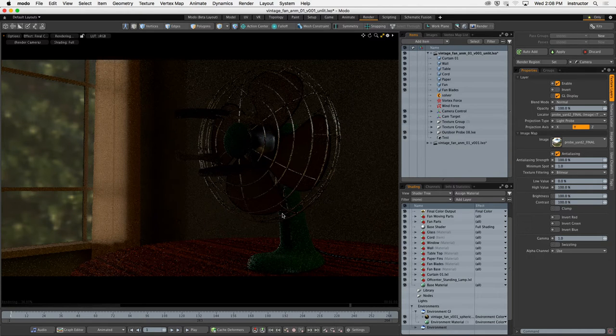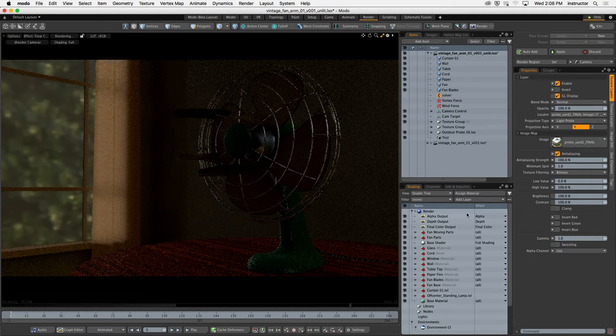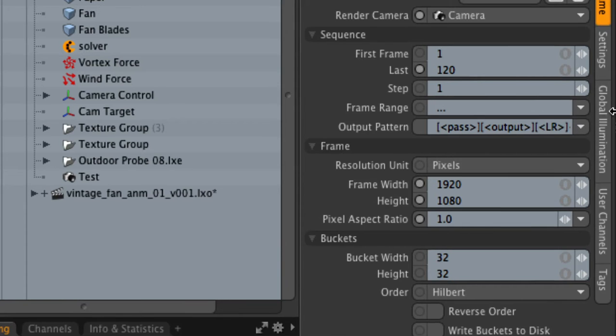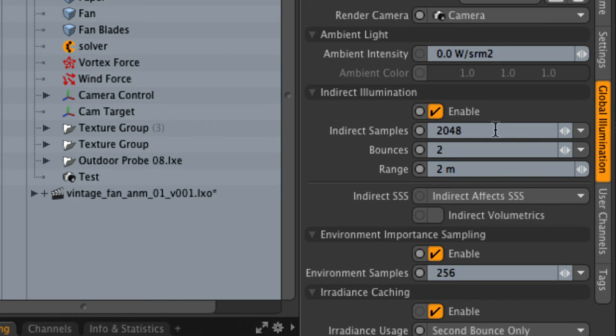The inverse of that is indirect lighting, okay? And that's found in the global illumination section of our render properties, of our render items. So global illumination, this section right here. So it's defaulted to on, and you guys are used to seeing that gray gradient show up in the background of your scene. We want to walk as far away from that gray gradient as we can. Gray is ugly, and it's going to wash out all of your colors inside of your scene, okay? So we want to turn off its influence, and we want to turn off its visibility.